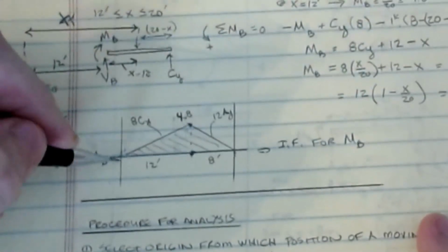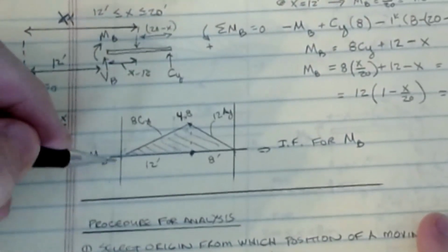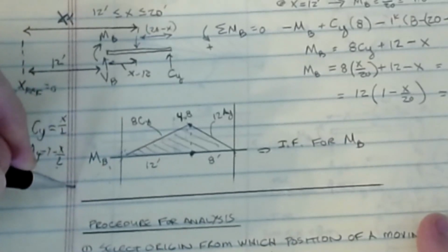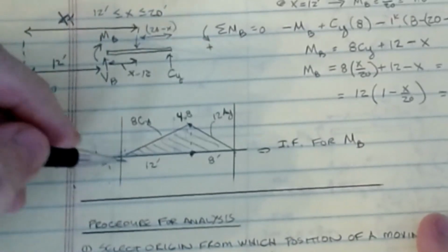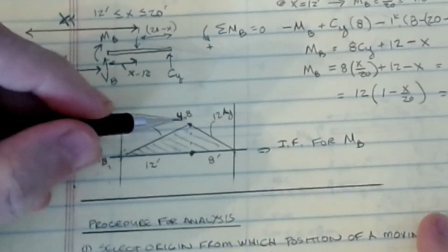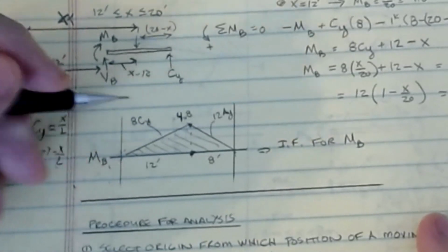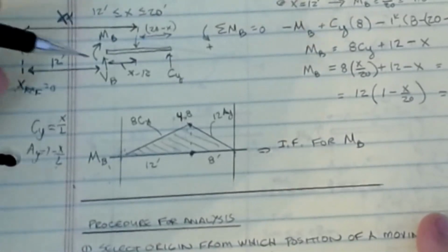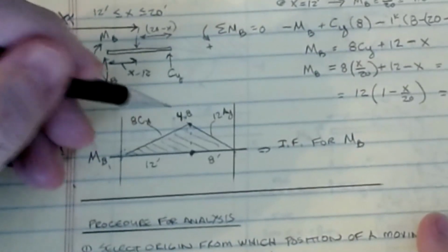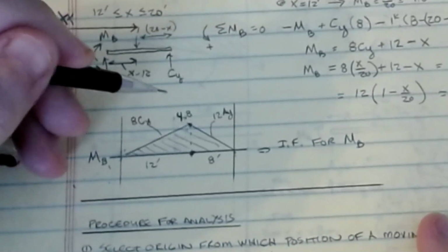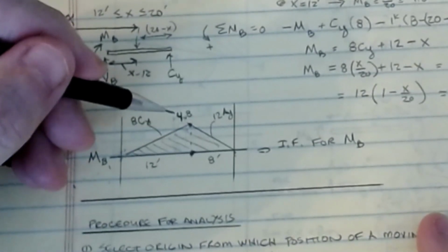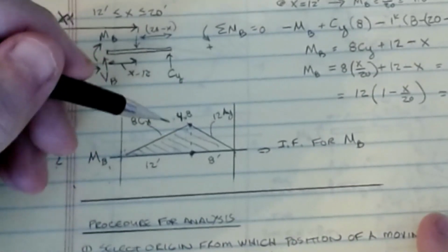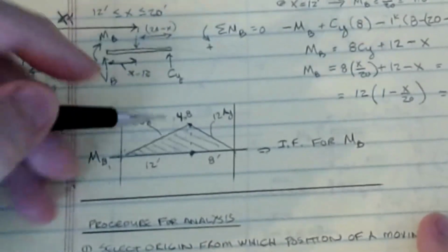Now, if you notice, it was 0 here. If I had a cantilever on this end, this line would continue down. And we'll take a look at one here in a second that shows that, in which I could actually get a negative coefficient, and that's possible. So for reactions, most of the time your values are between 0 and 1, but for moments, they never are, or almost never, I guess. It's possible, but very infrequently does that happen.